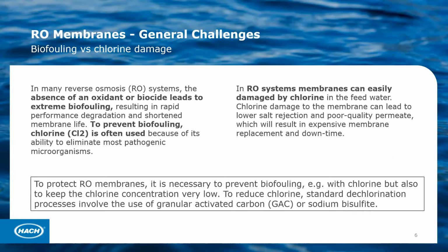There is the alternative of really concentrating on dialing in that oxidant feed, dialing in that chlorine so that we allow a safe amount of chlorine to pass through our membranes. That can serve as a disinfectant and a check on biofouling potential. But that is, of course, much more difficult to do.